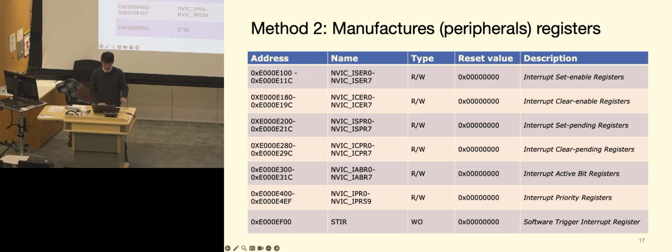Okay, perfect. So there are some advantages and disadvantages between them, as we briefly mentioned before. If we use the ARM-provided one, CMSIS, it's usually easier to read and maintain, and it's portable, compatible across different Cortex-M devices because that's implemented by ARM. But the disadvantage is you have one additional interface layer, which might slightly increase your code size if that became very important to you.